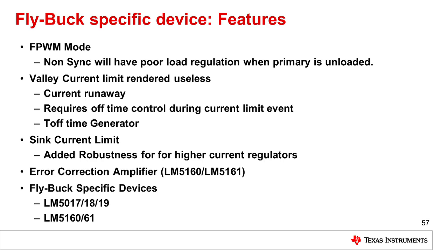Now, TI has several regulators that are specifically designed for Flybuck applications and that have all of these features you see on this slide built in. One such family is the LM5017, the 5018, and the 5019, and another example is the LM5160 and 5161.